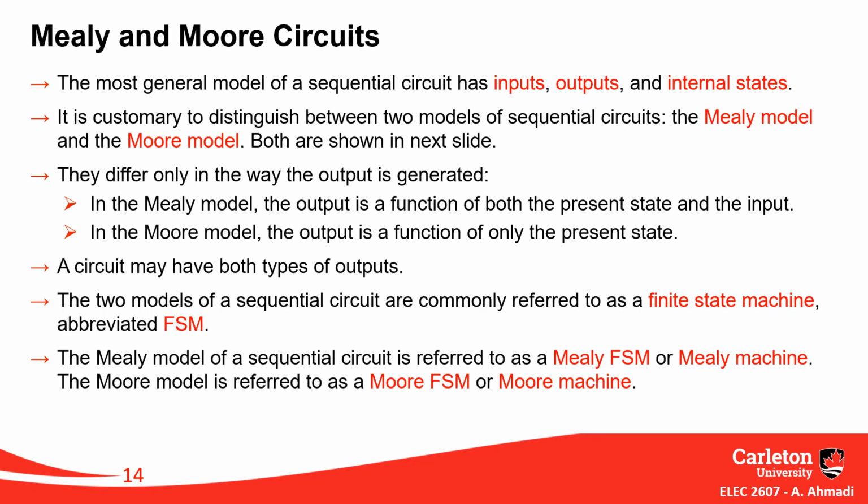Let's have a look at this. In my previous example, if I tell you that my circuit right now is in state S0, can you tell me what is your output right away? If you go back and have a look at that state diagram, you see if your circuit is at S0, your output will be definitely 0.